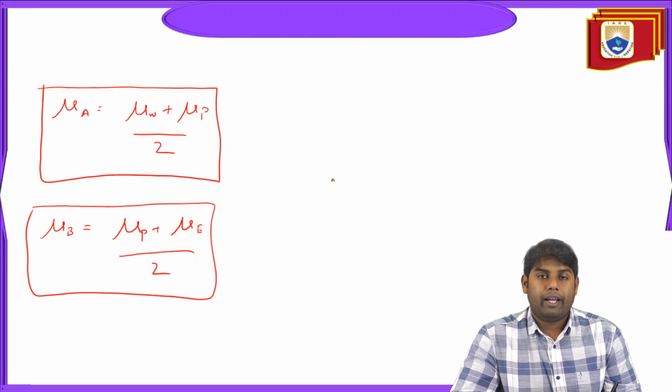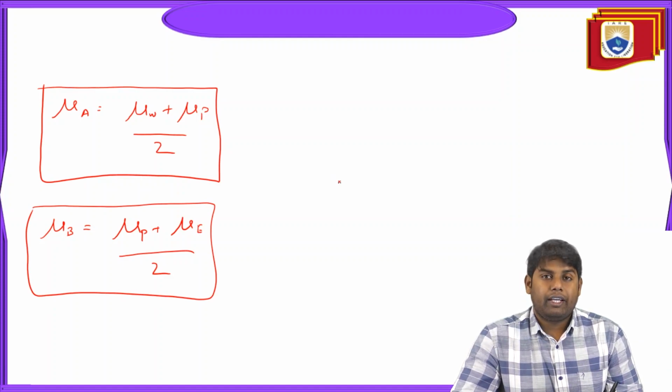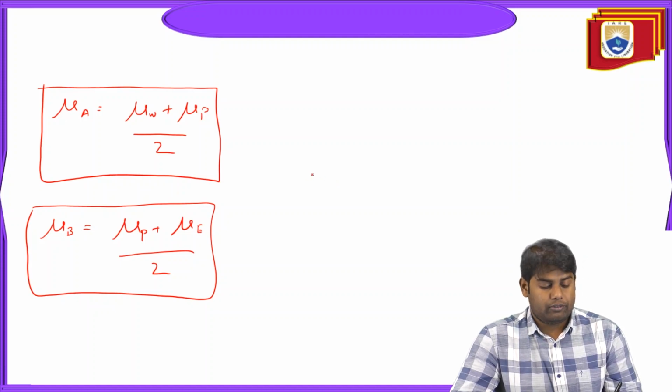Now what we have done actually is we have taken the average of the east node and the west node to get the value of the flux at the faces. Okay, so this is one of the approaches. This is a simple direct average that we are doing for 1D. So let us take 2D, 3D. Some other interpolation techniques are required. You cannot take a direct average. Let's say you have a weighted function.